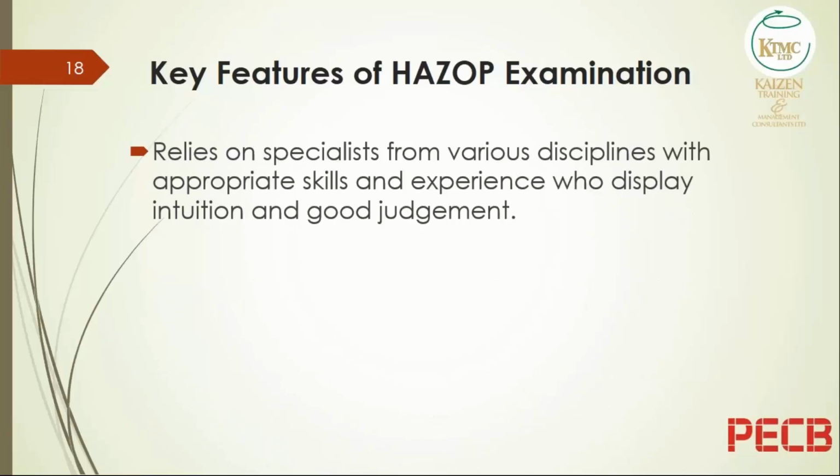The HAZOP examination relies on specialists from the various disciplines, as I indicated. So we must use appropriate skills: production, engineering, quality, design. We usually do not want the designer present in these studies because there is an inevitable bias. But of course, the designer must be available for consultation as required.